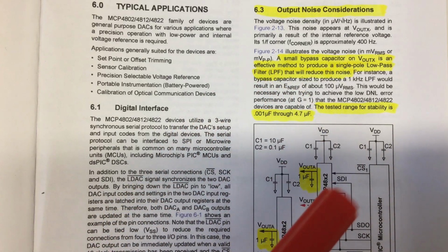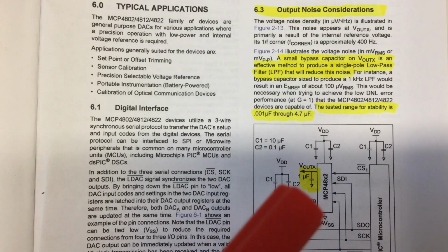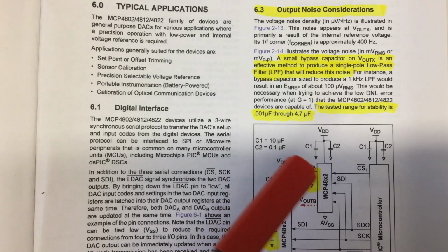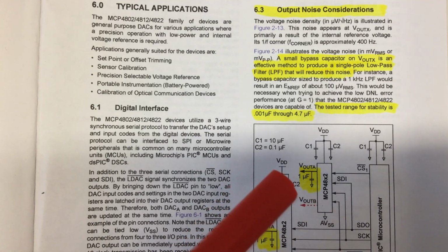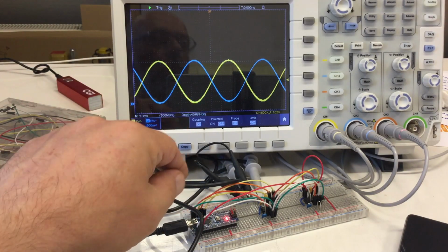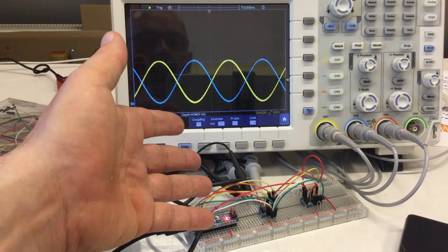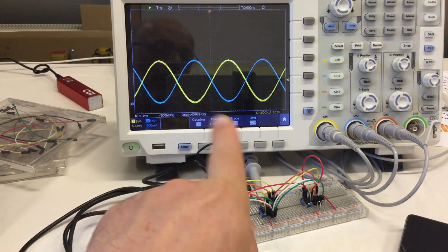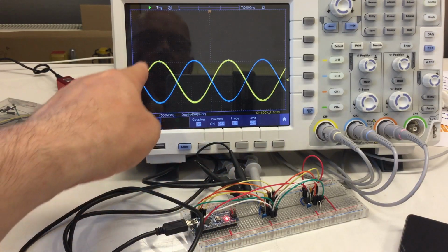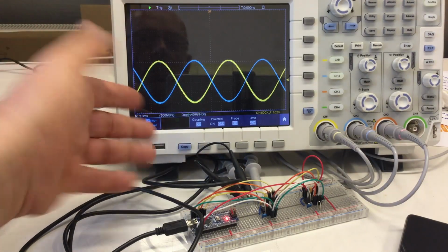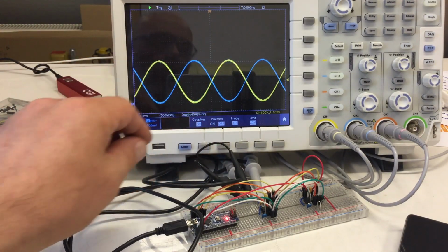Unfortunately, nothing in the datasheet gives us a hint about what the output impedance is, so we have no way to really calculate these capacitors. So yeah, we will have to experiment a little bit. I put a 0.1 microfarad capacitor at the channel A output of my MCP4822, and at the same time in software I switched off the use of that low DAC line. It's now always low again, so we don't see that nasty crosstalk here.